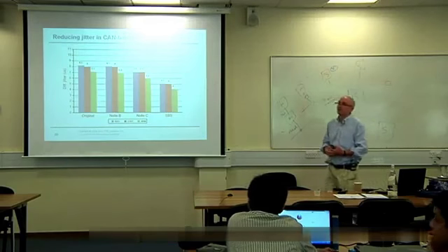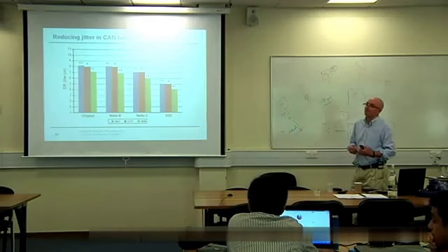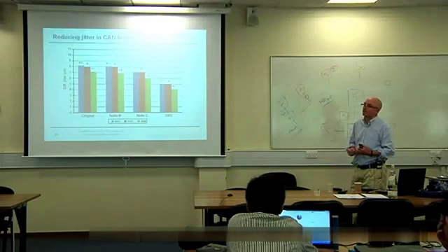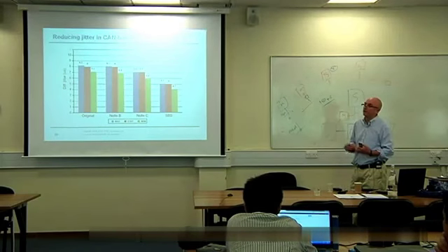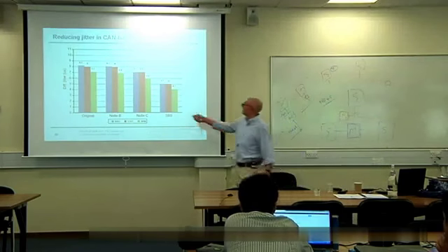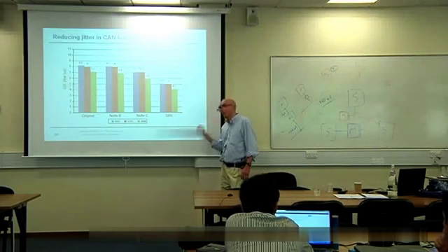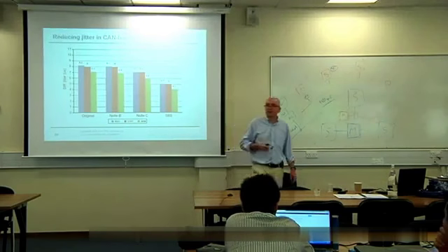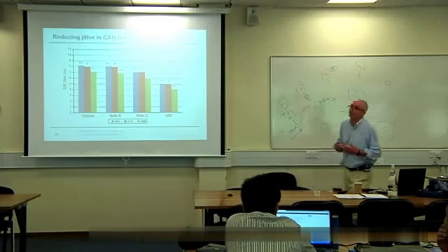If you invert the process, basically see how many ones are being sent in, and then you pad. You can pad for that, and that's what you do if you do software bit stuffing, but you can only do that in the part of the CAN message that you have control of.